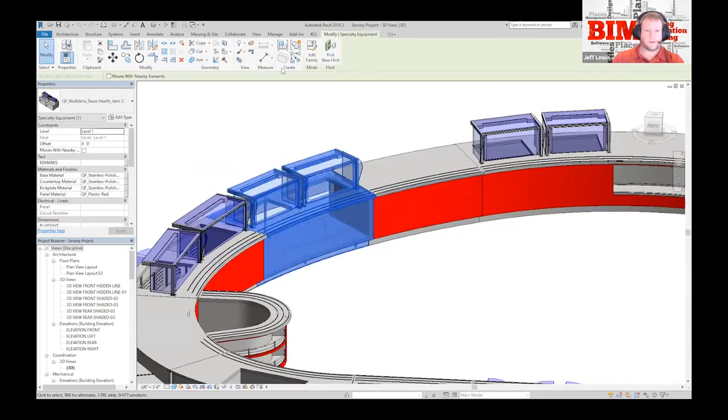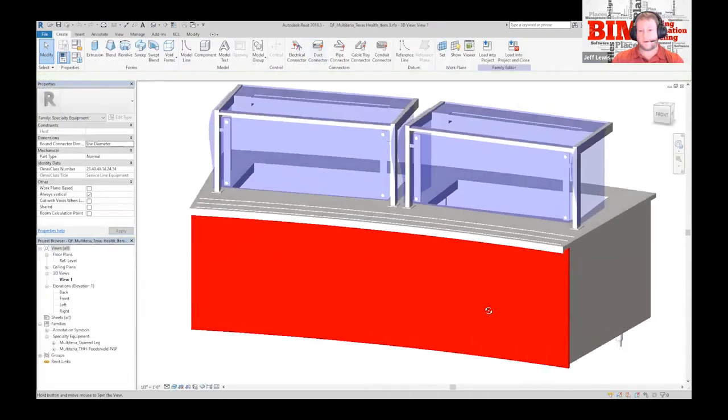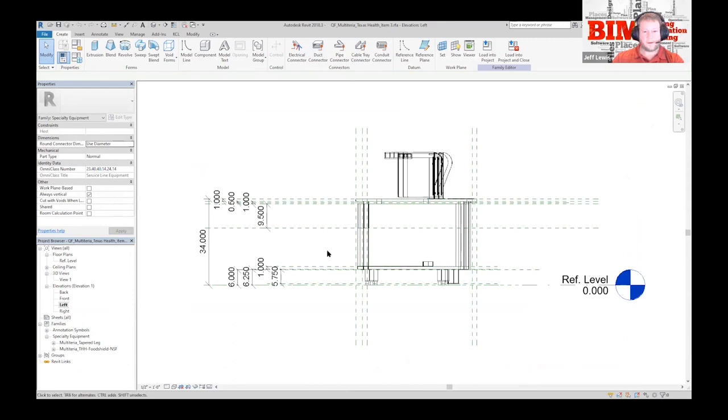So let's go into this curved piece. Instead of having the freedom to draw this as you would the cashier station or any straight piece, a lot of times sweeps will come into play. That's something you have to determine as you're going. But the biggest thing when you start the servery unit is you want to set up your elevations, because this will be consistent through every piece.